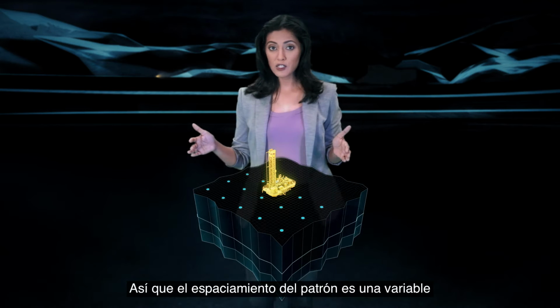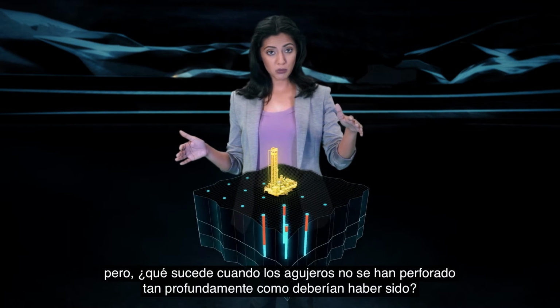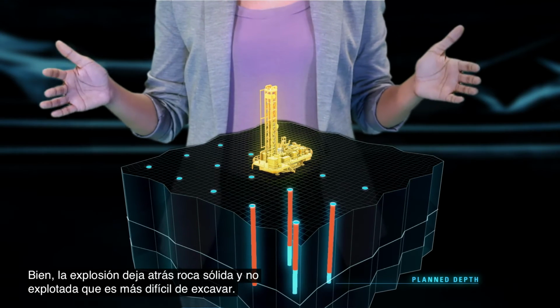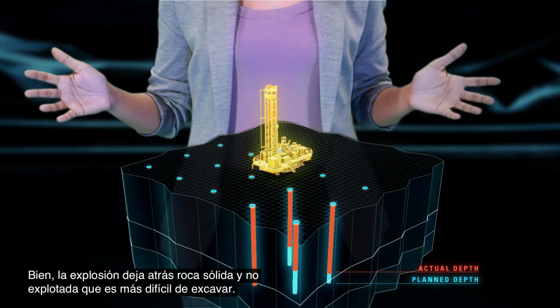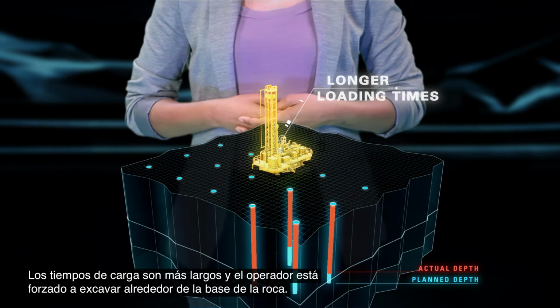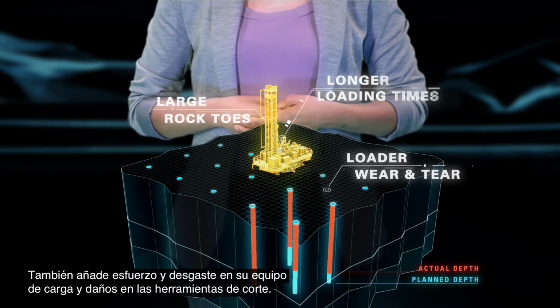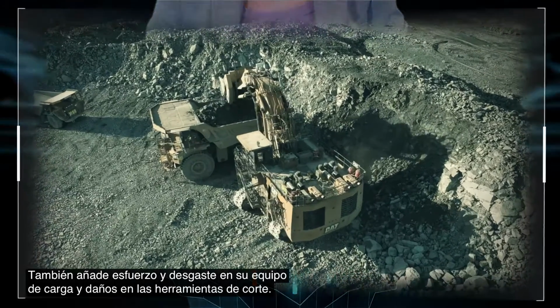So pattern spacing is one variable, but what happens when holes aren't drilled as deeply as they should be? Well, the blast leaves behind solid, unexploded rock that's a lot more difficult to dig. Loading times become longer, and the operator is forced to dig around the rock toes. It also adds strain and wear on your loading equipment, and damage to the ground engaging tools.